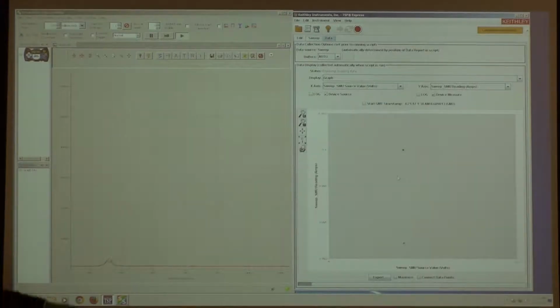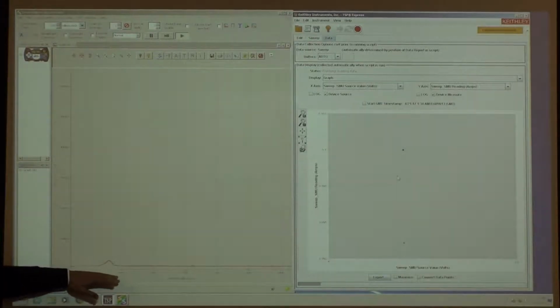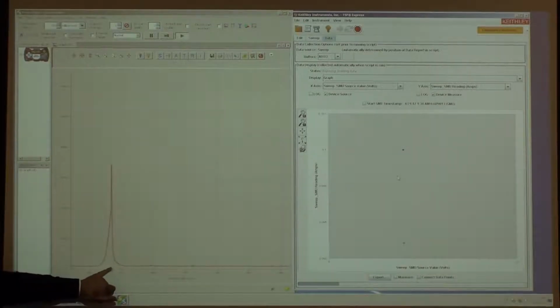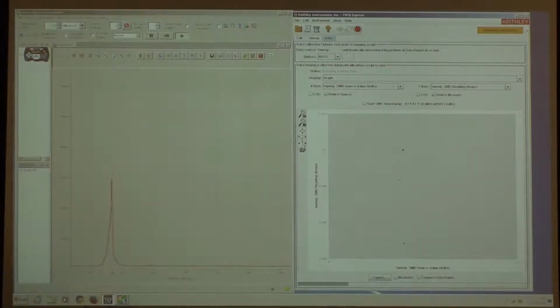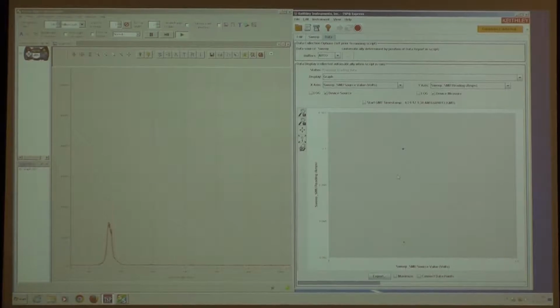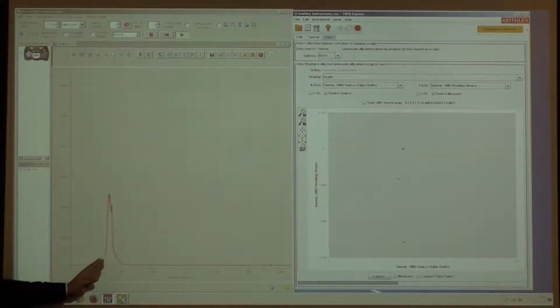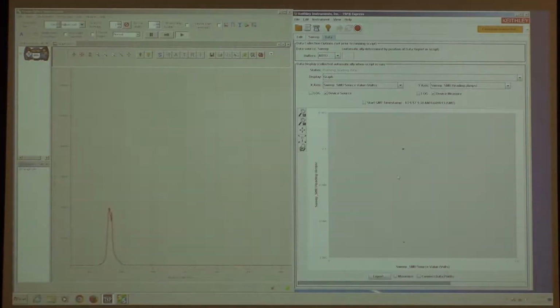So while they're doing it, this is the spectrometer. It's measuring photons at what wavelength. Here's the wavelength. You can see it's 400, yeah, you can see the 470. Maybe some 460 nanometer. That's blue, and you will see it with your eyes sometime. Hopefully, once it starts lasing, it's a really bright blue color. That's been designed with this quantum well structure. At this point, it's a light emitting diode. It's broad, so there's no lasing yet.